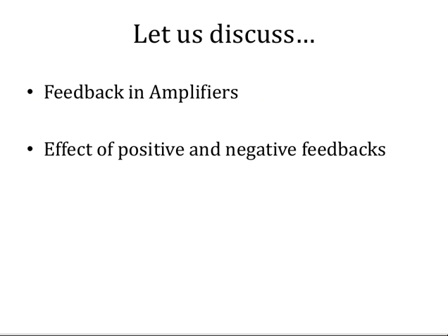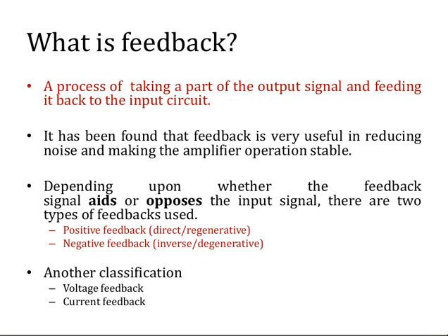In this lecture, let us discuss feedback in amplifiers and the effect of positive and negative feedback. So first of all, what is feedback? It's a process of taking a part of the output signal and feeding it back to the input circuit. It has been found that this feedback is very useful in reducing the noise and making the amplifier operation stable.